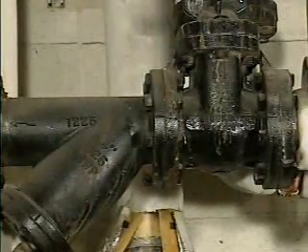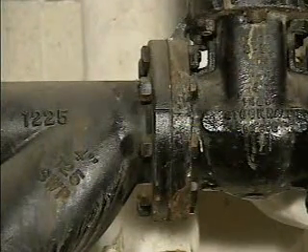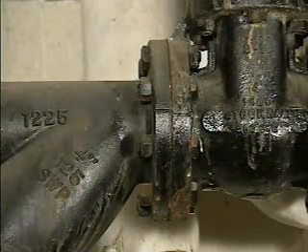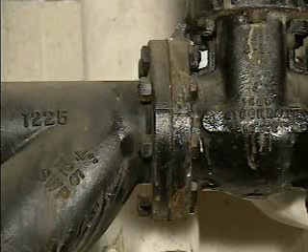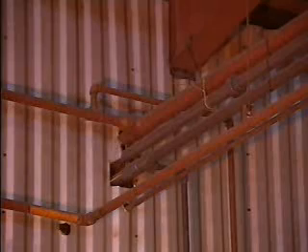Another characteristic of carbon steel is that it's less brittle than other materials, such as stainless steel, so it's able to absorb vibrations. Therefore, it is well suited for systems that generate significant vibrations, such as in vibrators used to make anodes and aluminum manufacturing processes, lifts, and large gearboxes attached to motors or turbines. Because it is susceptible to corrosion, carbon steel is generally used with non-corrosive gases and liquids.